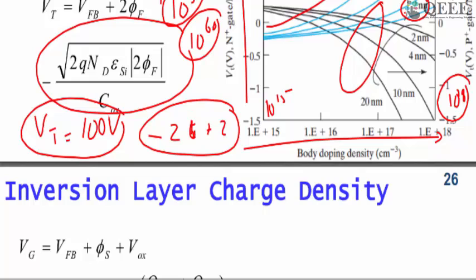Sometimes you utilize this to speed up the device. For example, in a diode or a transistor like a BJT, when it goes from the on to the off state, you need to remove all those minority carriers from the cathode, the anode side, or from the base. You can speed up the recombination events by selectively doping with gold or something like that. But it also has a downside: it may increase the leakage currents. So in short, Shockley-Read-Hall is a kind of recombination mechanism. There is a related question: the relationship between threshold voltage and leakage current.